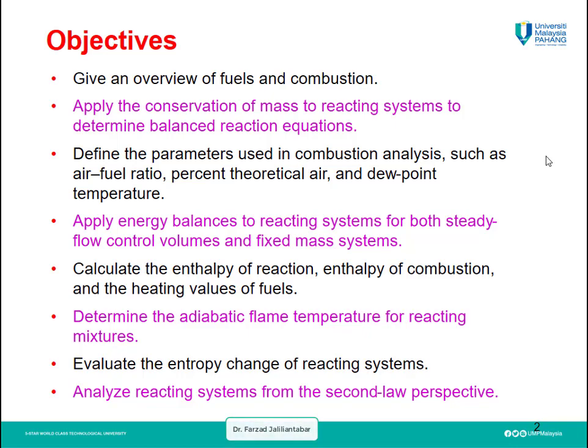And also we will see how to apply the energy balance for the reacting system, for both the steady flow control volume and also the fixed mass system, or closed system. And also we calculate the enthalpy of reaction, enthalpy of combustion, and heating value of different fuels. Moreover, we will determine the adiabatic flame temperature, which is an important parameter with different fuels, especially when designing